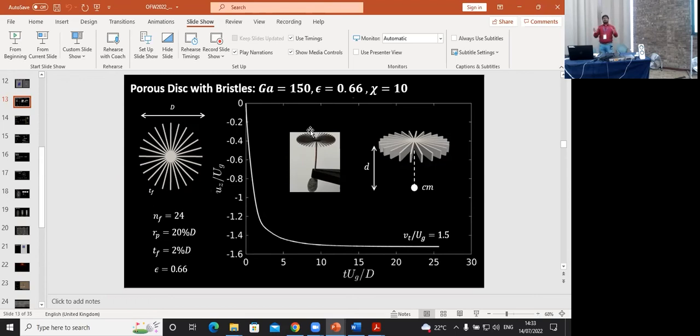So the 3D cases where I apply gust, currently it has a scale of around 10 million, but it is still coarse in terms of capturing the resolution of the flow field. So I basically use ARCHER2, 2 nodes, let's say 128 processors each, so basically 256 processors, and it runs for 5-6 days to capture the sufficient distance that I want to capture after reaching the terminal velocity.